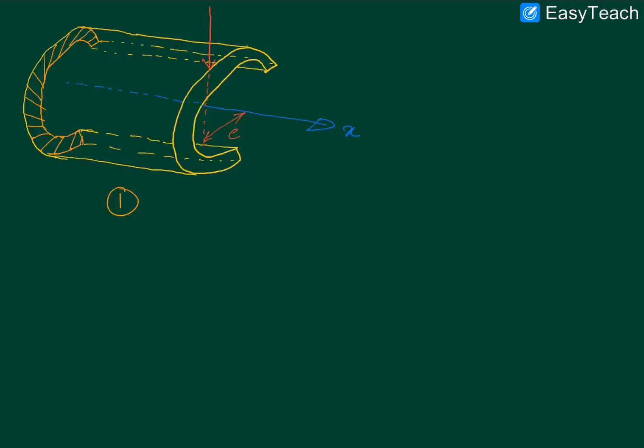And the easy part here has to actually do with the thinness of this section, because you understand that because this is such a thin section, there would not be any appreciable distribution or variation of shear stresses across this thickness. So across this thickness or across this thickness, there would not be any appreciable variation of the shear stresses.